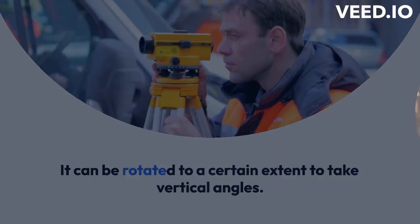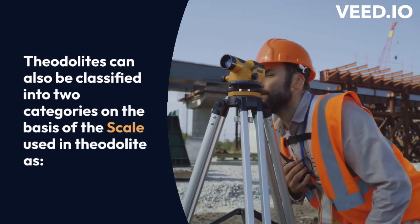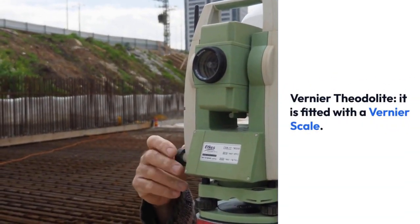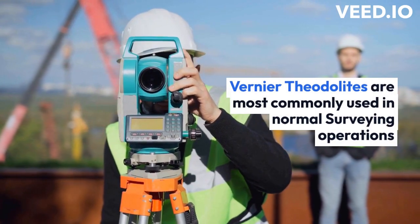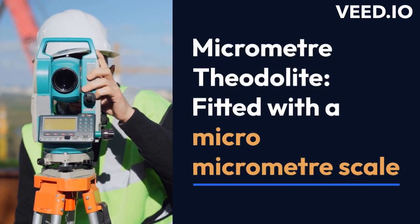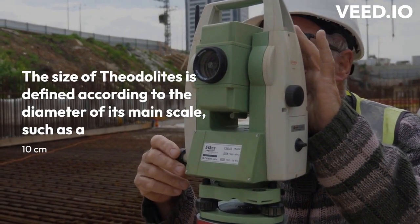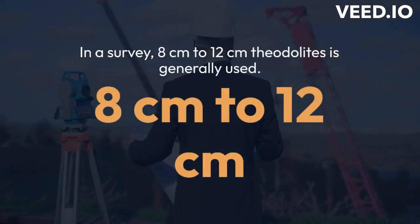Theodolites can also be classified into 2 categories on the basis of the scale used in the theodolite. Vernier theodolite. It is fitted with a vernier scale. Vernier theodolites are most commonly used in normal surveying operations. Micrometer theodolite, fitted with a micrometer scale. The size of a theodolite is defined according to the diameter of its main scale, such as a 10 cm theodolite means that the diameter of its main scale is 10 cm. In a survey, 8 cm to 12 cm theodolites are generally used.